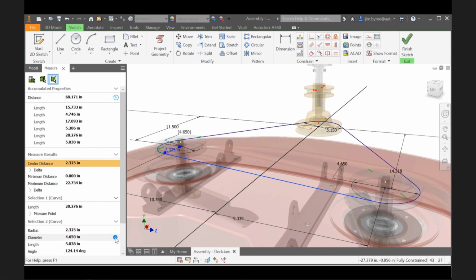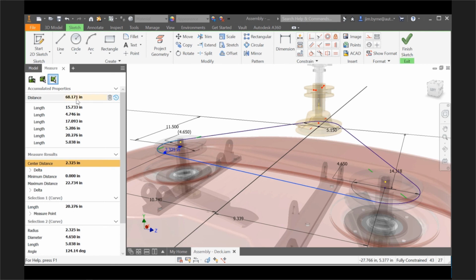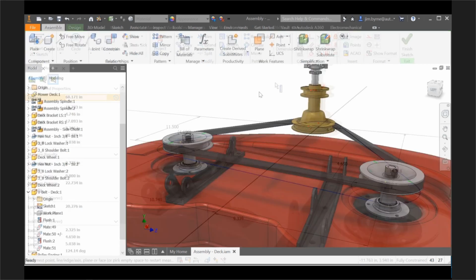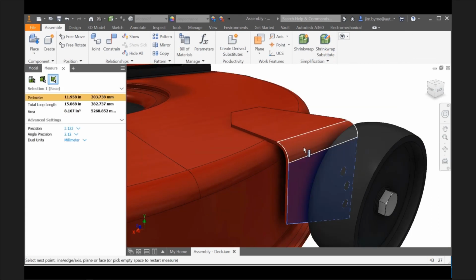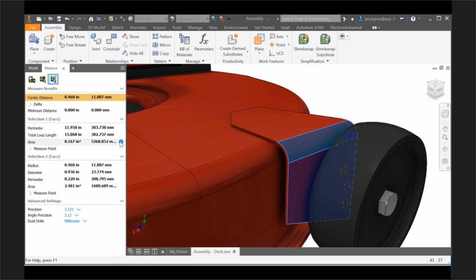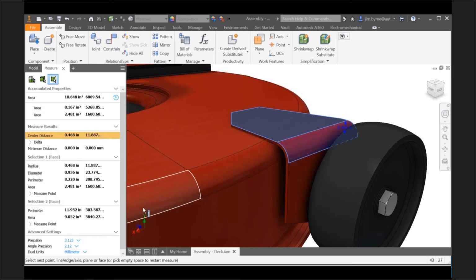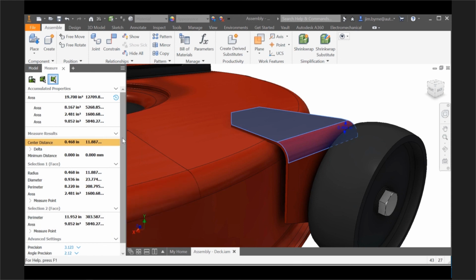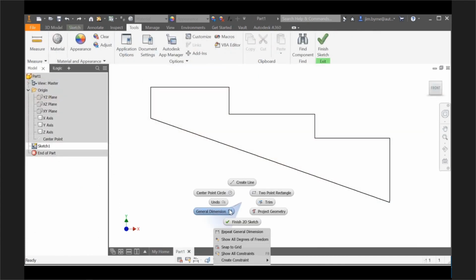On the top, you can see I've got different overall measured lengths, and the very top is the total accumulate. You can delete individual or total values from that measure accumulate. Here you'll see, as we go back into measure, we'll select different things like surfaces. So if you're looking for total surface area for painting or different applications, you can see that those are in there. It'll actually bucketize those. So if I have linear measurements and surface area, it would separate those.